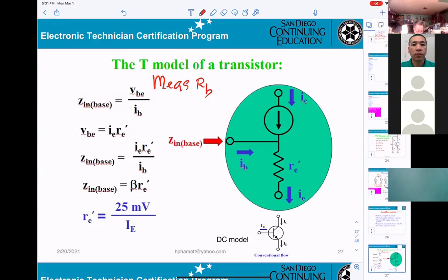On this hand now, they're using V in, same thing as RB, doesn't matter. And the formula for Ohm's law will be equal to V at the base divided by the current IB. That's why you get RB. So in general, that will be VB divided by IB. I already talked to you: they're using uppercase for DC and lowercase for AC.